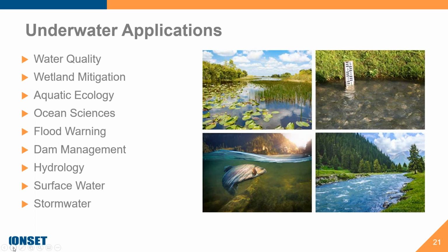How these are used, lots of water quality studies. Sometimes third-party sensors can be added if you're doing mainly water quality. So water level, of course, is typical. Wetland mitigation, you're adding dissolved oxygen data loggers that can be added to give you a wide parameter, and temperature sensors, of course. Flood warnings for the water level data loggers in dam management type applications.